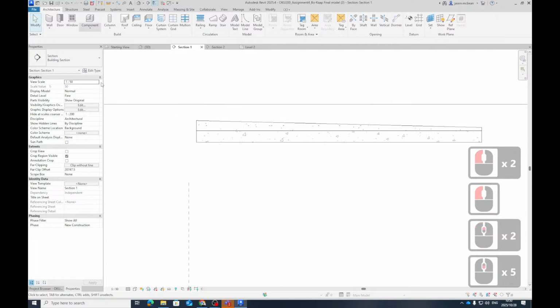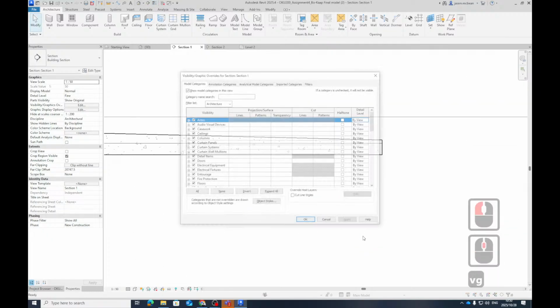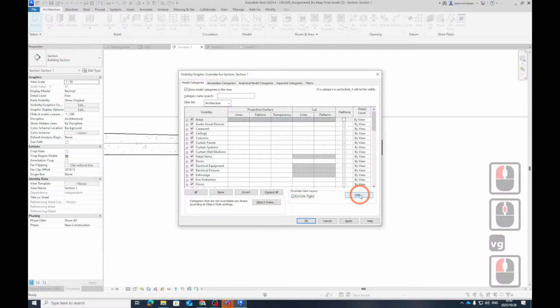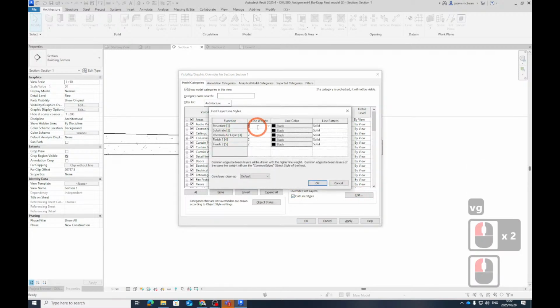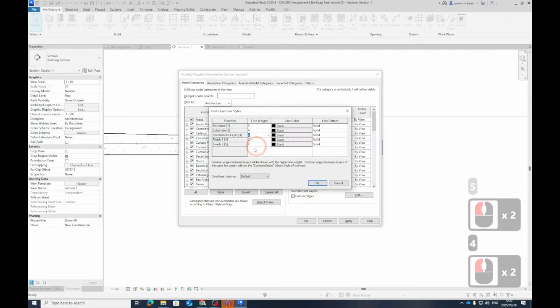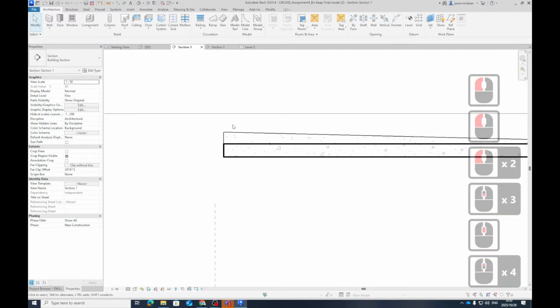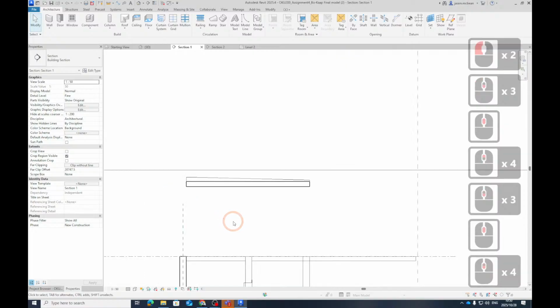Now we switch on your line weights, you'll start seeing this better. Now, this is the only trick, VG. You're going to cut things by their importance, so structure, always 5 or 6 depending on your concrete. Substrate, that's 4. The rest can remain the same, just like this. Press apply. So there's your concrete. Oh, thank you so much. Easy, huh? Easy peasy.